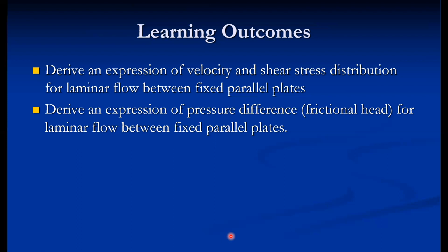The only thing is that at the beginning we cannot take integration for obtaining the expression of shear stress, because we don't know the boundary conditions for shear stress at y equal to 0 and y equal to D. We know that shear stress is maximum at the boundaries, but what is the magnitude of that shear stress, we don't know. That's why here we turn the derivation around: first we develop the expression of velocity distribution, and then we develop the expression of shear stress according to Newton's law of viscosity. Otherwise, the procedure remains the same.